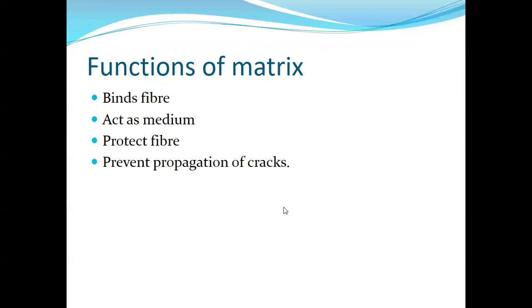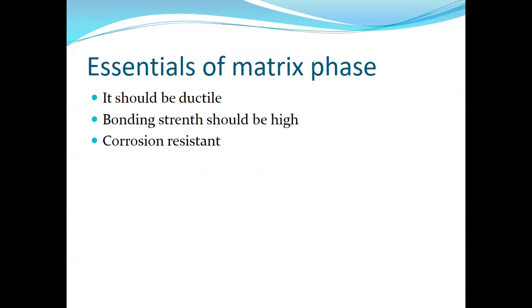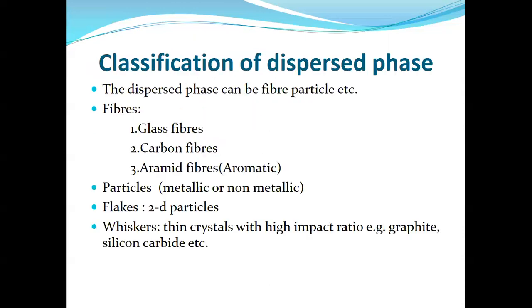Then, functions of the matrix. It binds the fibers, acts as a medium, protects the fibers, and prevents propagation of cracks. These are the functions of the matrix. Essentials of the matrix phase: it should be ductile, bonding strength should be high, and it should have corrosion resistance.